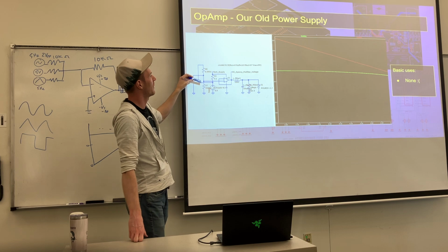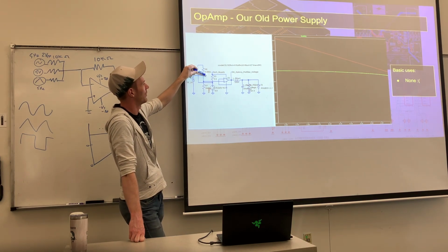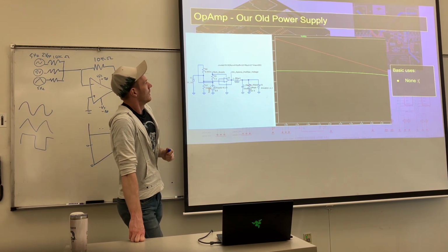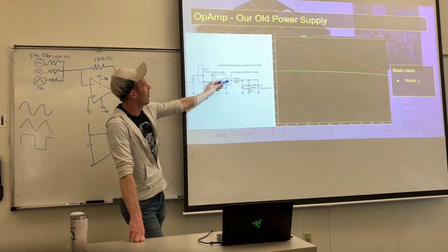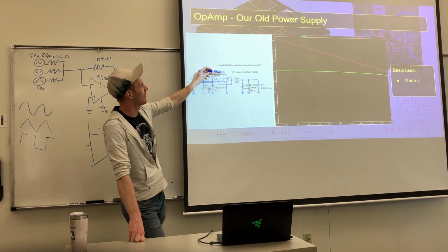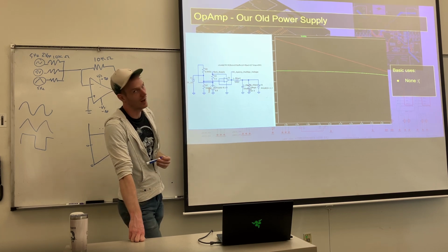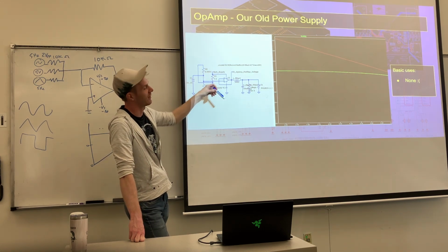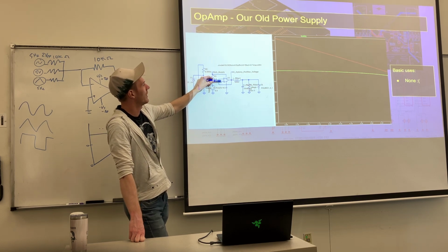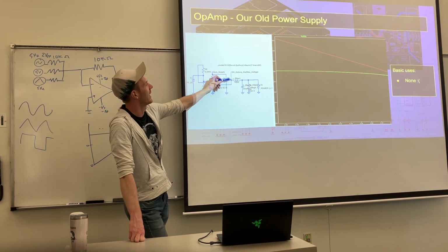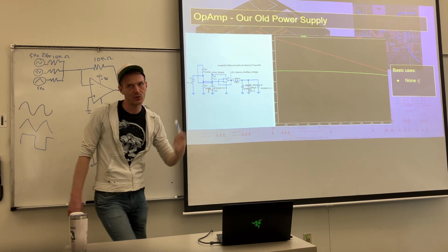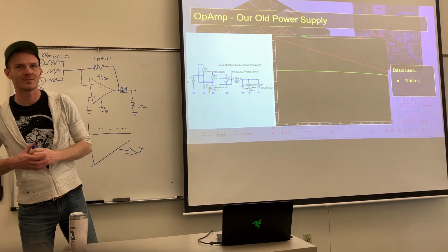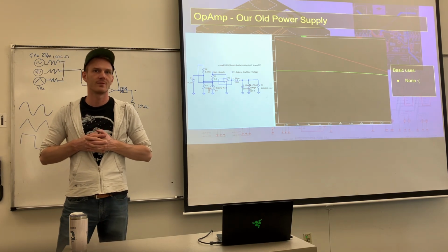Now with what we just talked about with the op-amps, we're taking that 5 volts and sending it to the non-inverting terminal. Then we have the inverting terminal hooked up to the output, and our supply voltages are the battery and ground. We don't care about the negative voltage, there's never gonna be a negative signal. But what is happening here? We're sending 5 volts here, and the feedback is coming to the inverting terminal. Think about how I first described that amplifier. Do you have an idea? It's going to slowly build up until it matches the input.